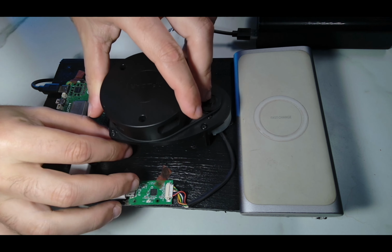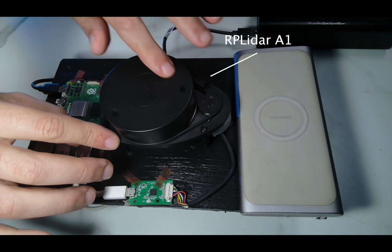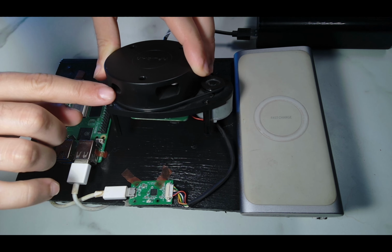The working principle of a LiDAR is very simple. Luckily, I actually have a LiDAR with me and we can have a closer look. So this is a very low cost, very accessible LiDAR sensor. It spins like this, and while it is spinning, it shoots out an infrared laser, so we can't see it. This laser beam will travel in a straight line.